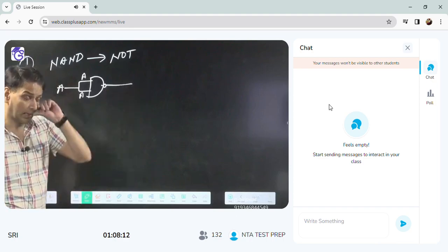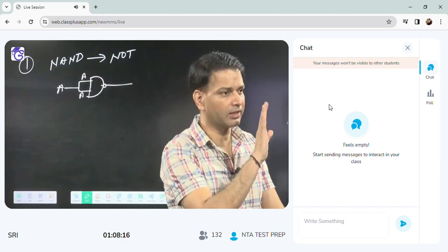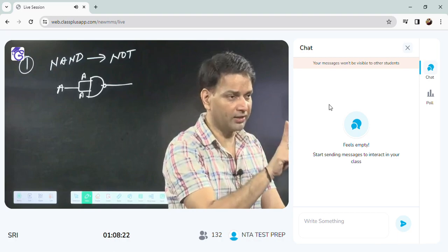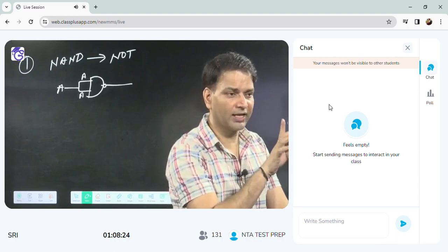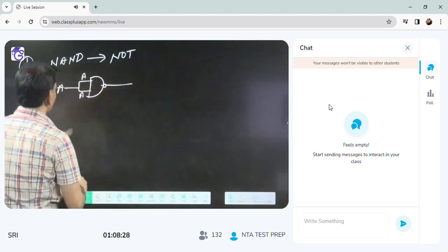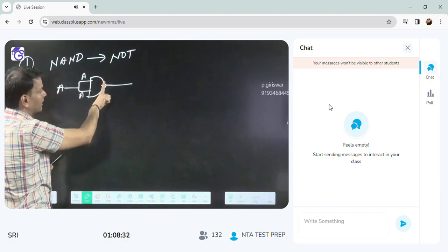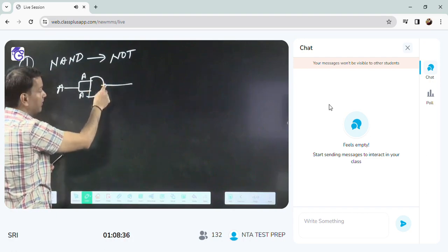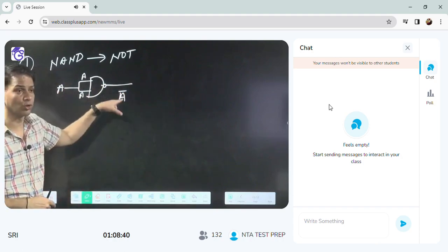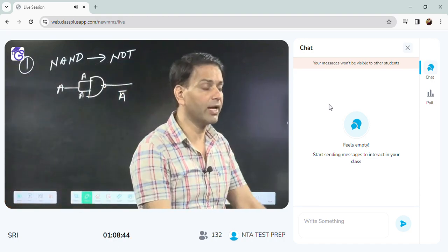Now listen, first we will do the AND, then we will do the NOT. So the input of the NAND is A and A. So first do the AND, A dot A, which is A. So AND gives A, but we need NOT AND. Then what will you get? A bar. Forget about this circle. The AND process you have to do. AND means multiplication, A dot A. But you have to take the NOT, so you got A bar. Now you took the input A, the output you got is A bar. So that is the NOT gate. So by using NAND, we have got the NOT.